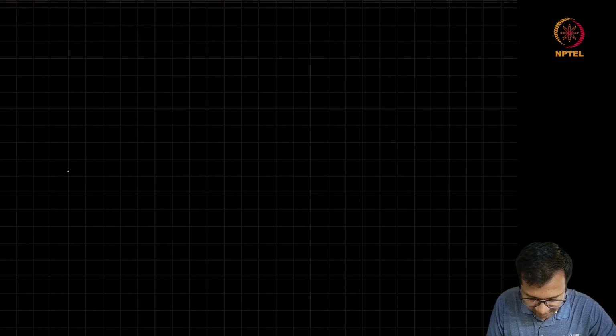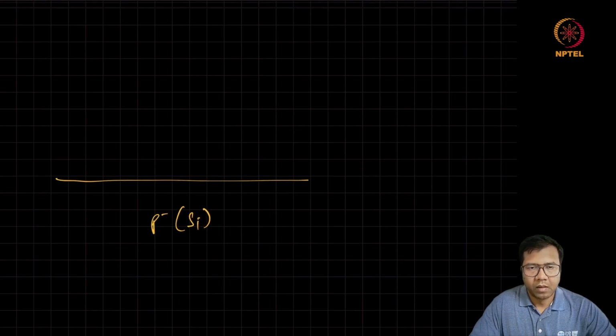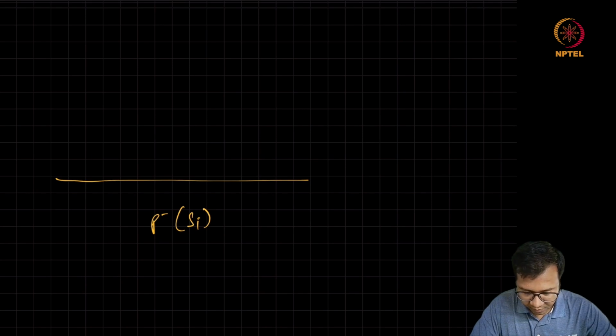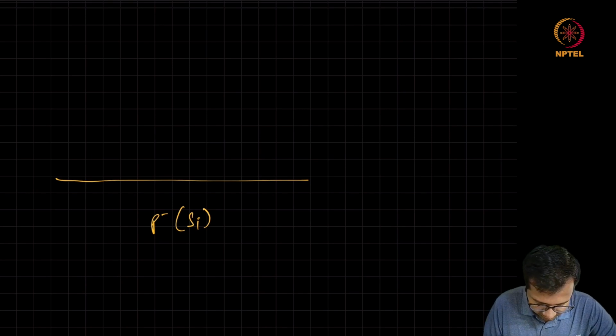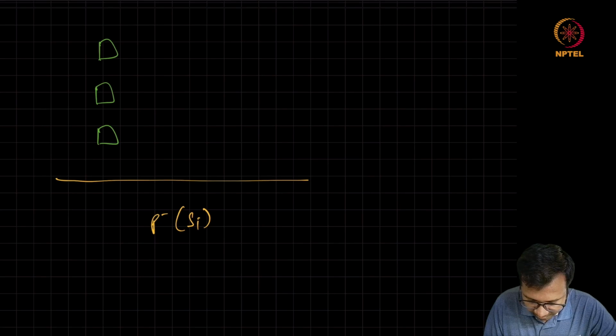The on-chip capacitors are fabricated on top of a substrate. So these metals will be, let's say, here. Similarly, this MIM capacitor can have a specialized layer.